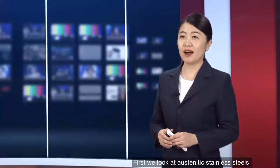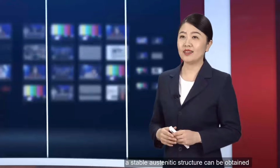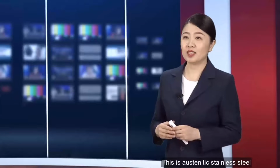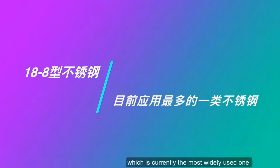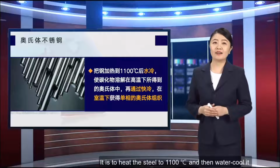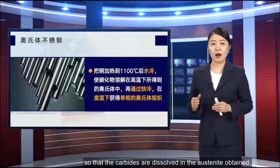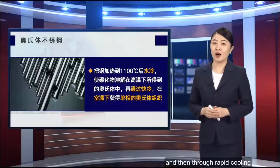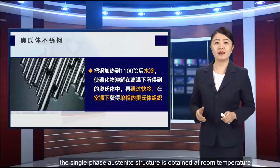First we look at austenitic stainless steels. When the steel contains 17 to 19% chromium and 8 to 11% nickel, a stable austenitic structure can be obtained. This is austenitic stainless steel, often called 18-8 type stainless steel, which is currently the most widely used kind of stainless steel. It is to heat the steel to 1100 and then water cool it, so that the carbides are dissolved in the austenite obtained at high temperature, and then through rapid cooling, the single-phase austenite structure is obtained at room temperature.